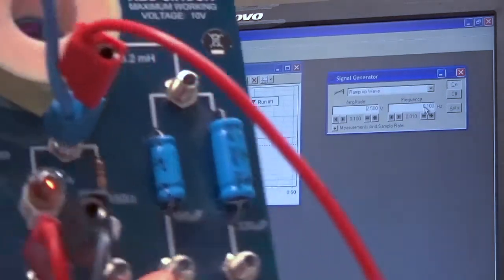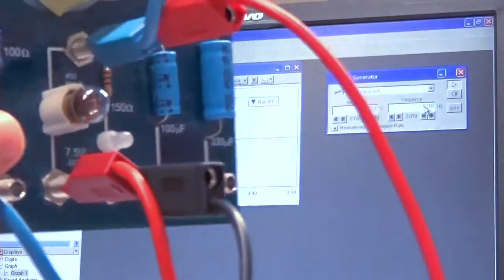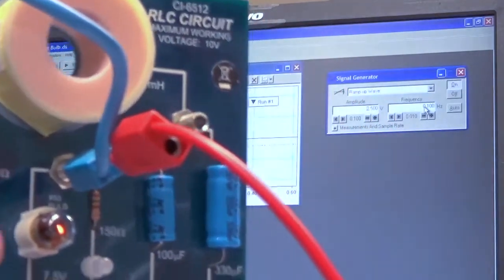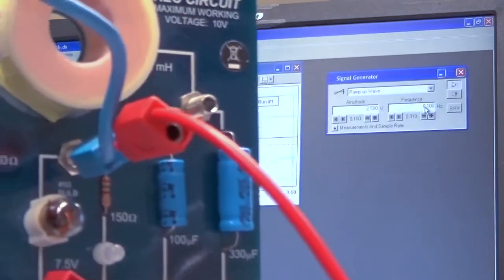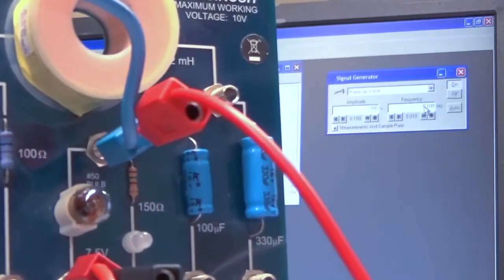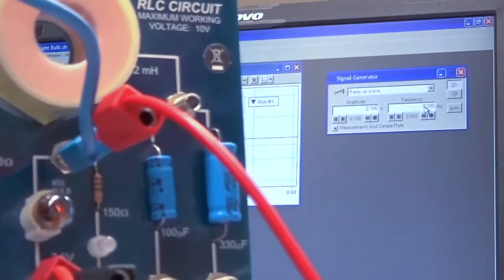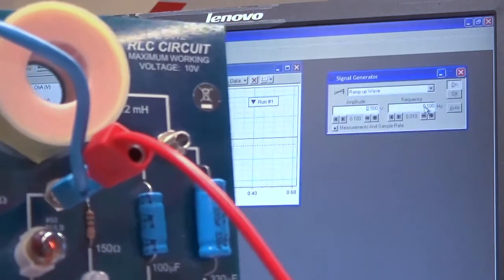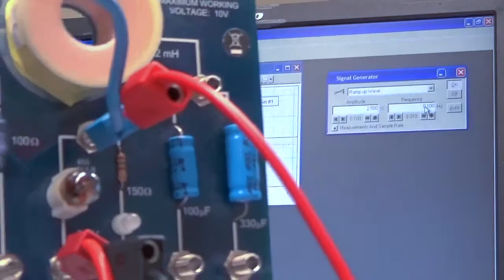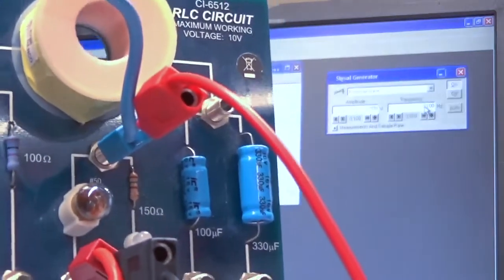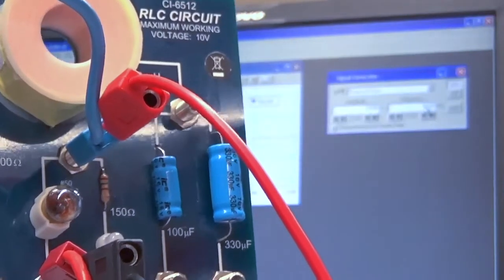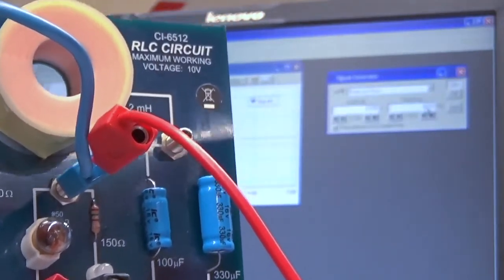If you have a look over here, you can see that light bulb is actually turning on and off. Now you can see it slowly turning on and off, which is an indication that that voltage of 2.5 volts is being applied at a very slow rate. In that case, that light bulb is not being supplied with enough voltage to reach its maximum operating temperature, for which it would be glowing constantly in a white light.